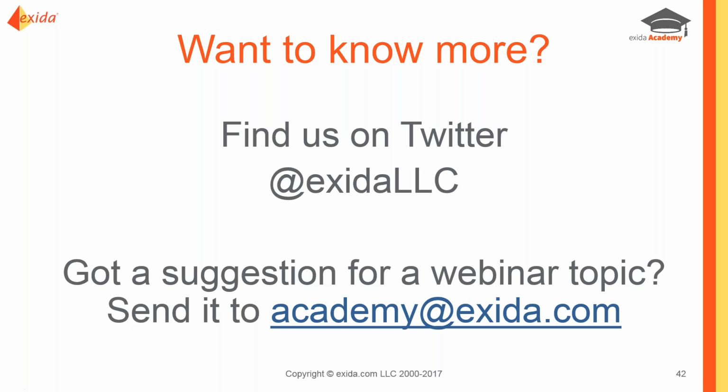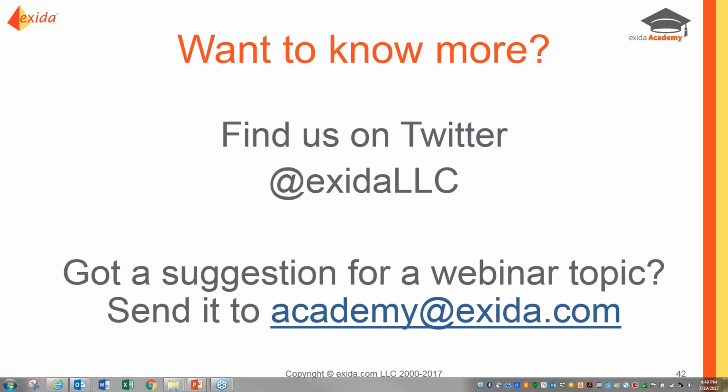So I'm going to look over here to the questions list. Well, we got a quiet group this afternoon. Hi, thanks for the very informative presentation. If we need a SIL 2 SIF and there are 2 valves in series, 1 XV on-off valve and 1 control valve, final element voting is 1 out of 2. If we want to use certification versus prove it in use, does each valve need to be certified for SIL 2 application, PFD average of 1 out of 2 voting, and the required range of the SIL?